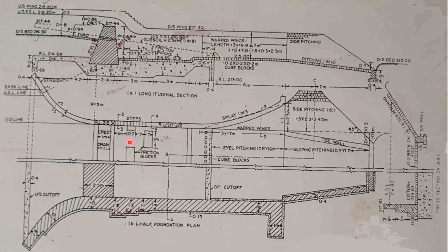So if you are going to draw a section here, this thing will be on both sides, that is, at this portion the section is rectangular only. So we can see here, this portion is the abutment of the crest wall, and it can be provided stepped or as a trapezoid, just like an embankment. So these dimensions are not needed because we haven't designed the dimensions of this abutment wall.